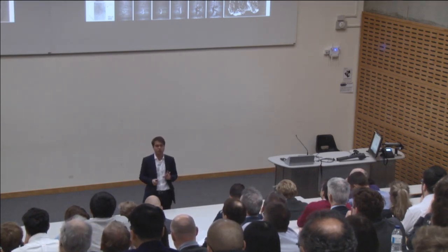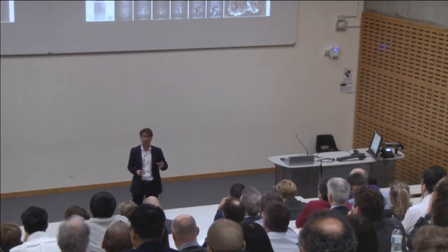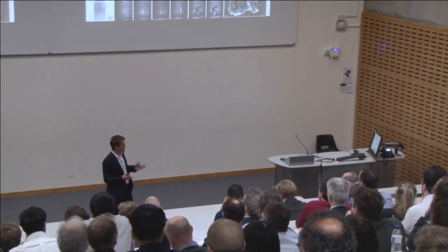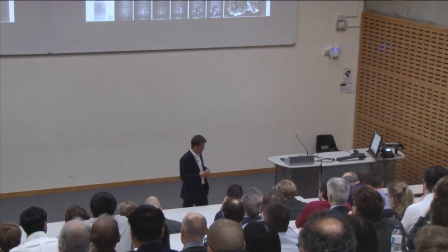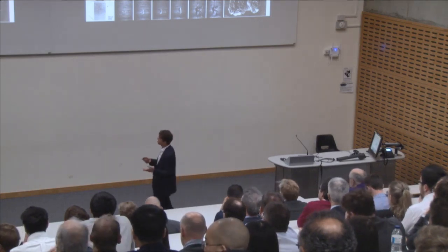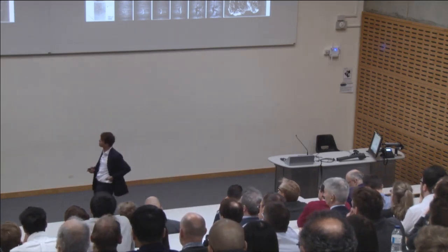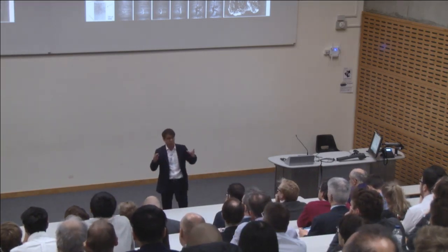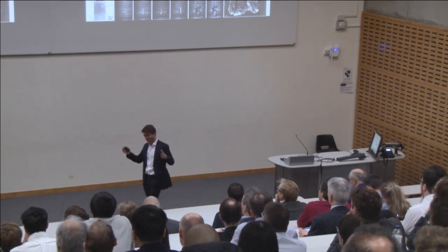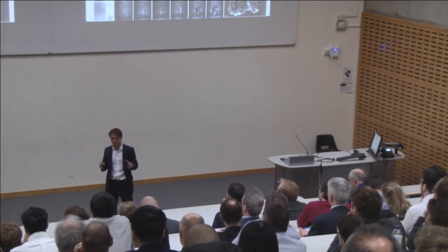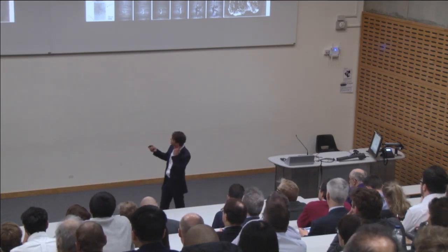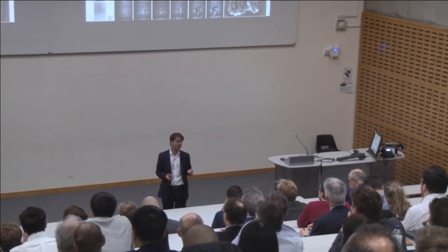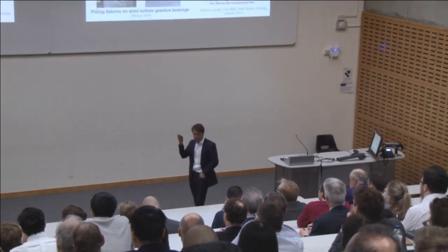Historically, subsurface initiated rolling contact fatigue was more significant because the crack started at subsurface non-metallic inclusions. However, with steels getting cleaner and some other developments in tribology that changed the contact conditions, we are seeing that in modern machines surface-initiated rolling contact fatigue is actually much more significant. It manifests itself in 2 major modes. One is pitting, where you get pits of the size of the order of the contact size, hundreds of microns to millimeters, such as in this bearing, or micropitting, as the name suggests, where the pits are much smaller, size in tens of microns.